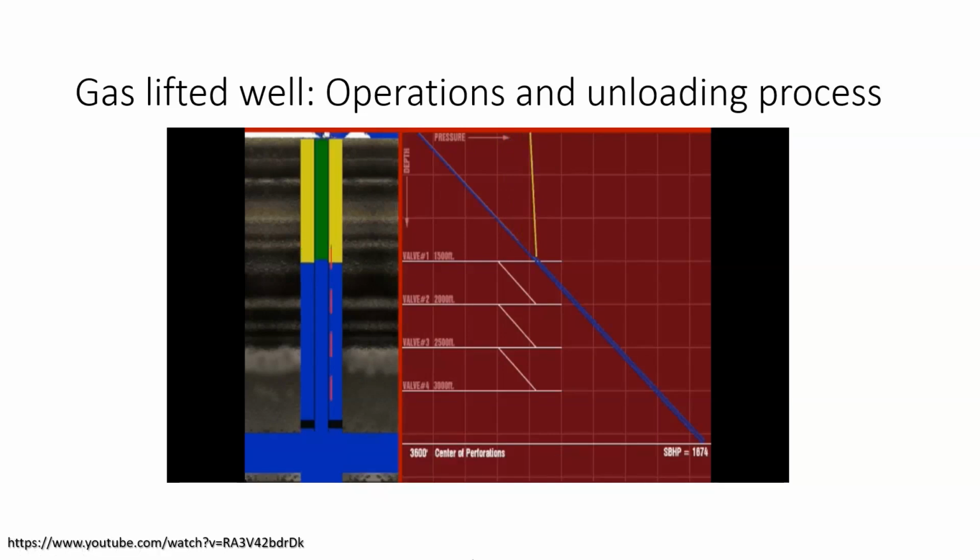This pressure is sufficient to lower the casing fluid below the first mandrel and allow gas injection into the top valve. This injected gas causes a lighter gradient in the tubing, allowing the well to unload the kill fluid entering the tubing string from the lower valves as the well continues to unload.